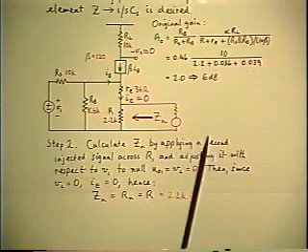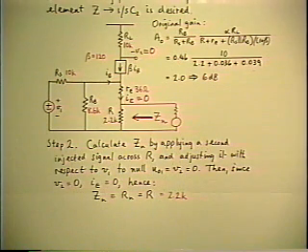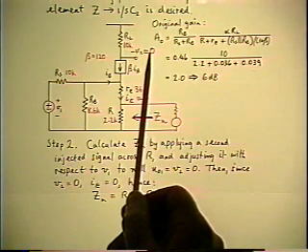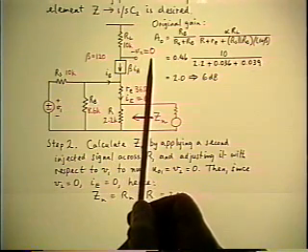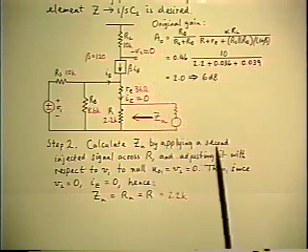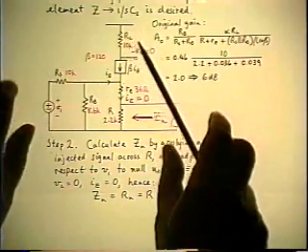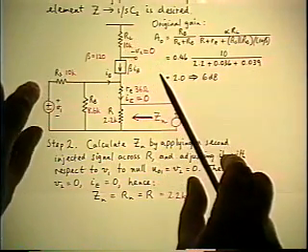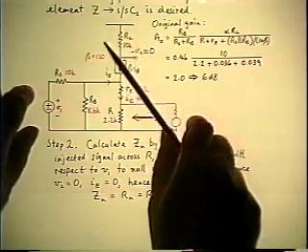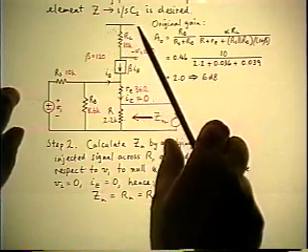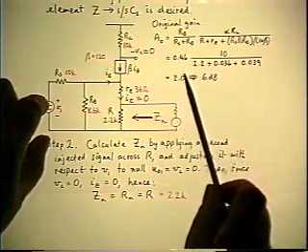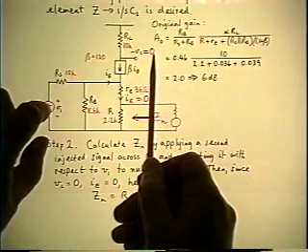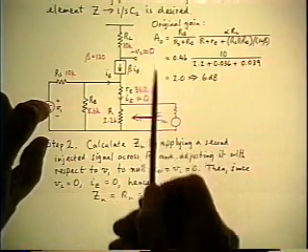But we have to adjust those two sources to achieve a specific condition. Namely, output number 1 is null. Output number 1 is V2. So you visualize twiddling the knobs, actually using one directly from the generator and the other one going through the shoebox with magnitude and phase knobs. And you twiddle the magnitude and phase knobs of the second input relative to the first one until the meter hung on V2 goes to 0. Then you don't twiddle anymore.